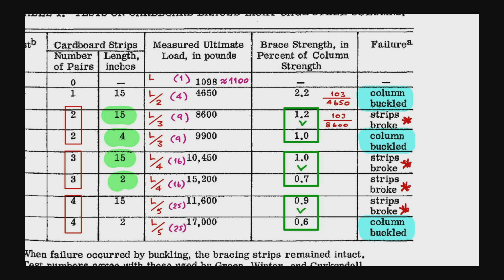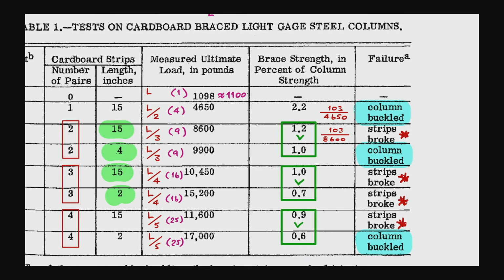maximum capacity, and if you use it to measure the load, which is around 1 or 2 tons, the resolution will not be so good because by design, it is made for high load. So if you measure small load, you better use the small load cell. You don't use just a high load cell, and each increment's reading is going to be very coarse. So back to our business here.